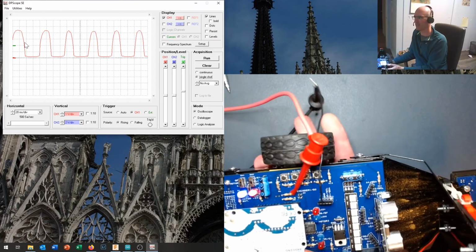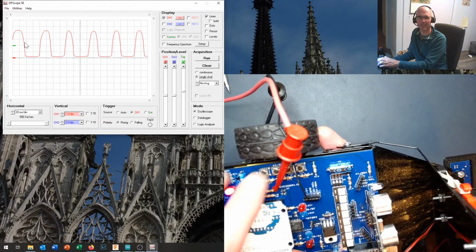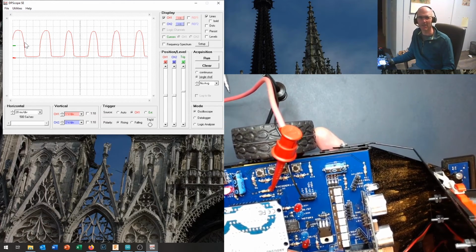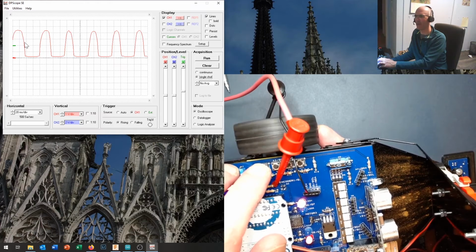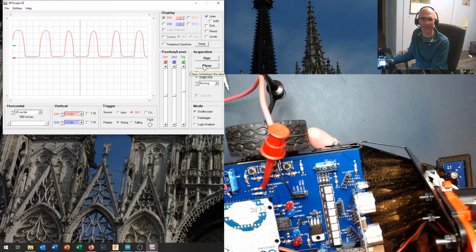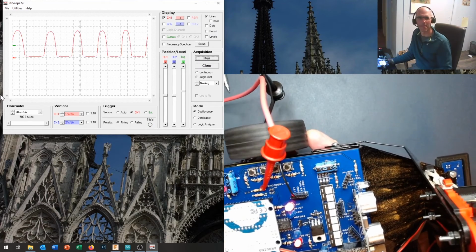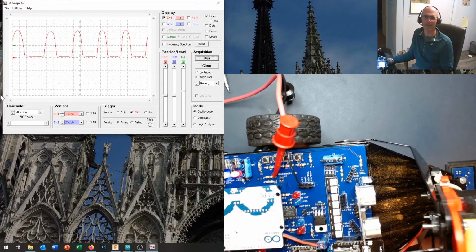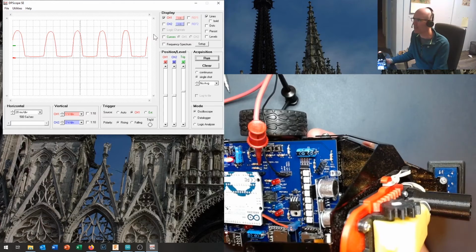I'm going to just hold on to this right here, and I'm going to show you what this looks like when your motor tries to run with just a little bit of drag on it. Now keep in mind that here we got 6 pulses in per 400 millisecond screen. We'll run that again with a little bit of drag on it. Oh, sorry, I need to set that up again and tell it that I wanted another shot on here. Let's clear that, run that, and with a little bit of drag on there, you'll now see that on that 400 millisecond screen, I see 1, 2, 3, 4, 5, and the sixth one doesn't quite get on there.